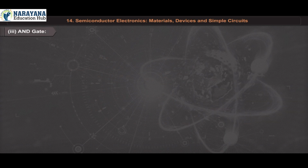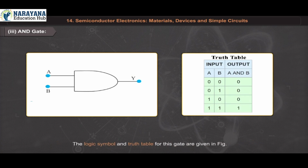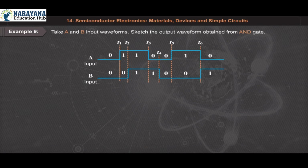Number 3. AND gate. An AND gate has two or more inputs and one output. The output Y of AND gate is 1 only when input A and input B are both 1. The logic symbol and truth table for this gate are given in figure. Example 9. Take A and B input waveforms. Sketch the output waveform obtained from AND gate.